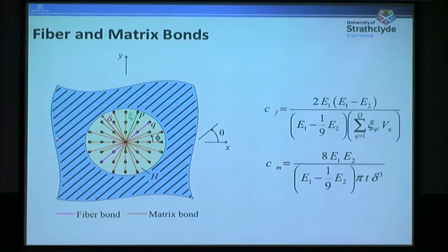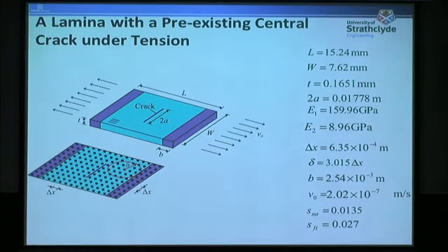In this particular case, since the fiber direction is the strong direction, we introduced a different bond constant in the fiber direction to make that direction stronger. And all bond constants that we introduce in Peridynamics can be calculated in terms of the material parameters in classical mechanics.